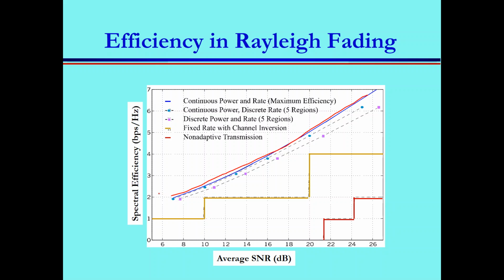When you can change the power values and the modulation order continuously, you asked me whether there is a space between the curves. If you have continuous values, then you have an infinite number of these curves. You can switch to any of them based on minimal changes in the signal to noise ratio. But this will complicate your system and make it extremely difficult for the receiver. The mapping table will get large, the complexity of detection increases, and there are many issues with too much complexity. That's why they don't use it in practice.